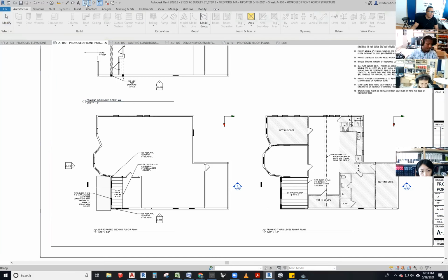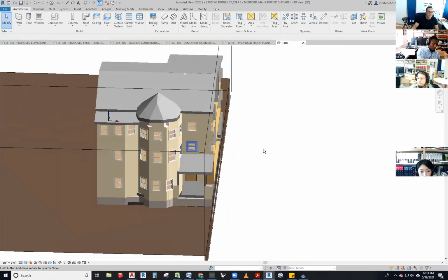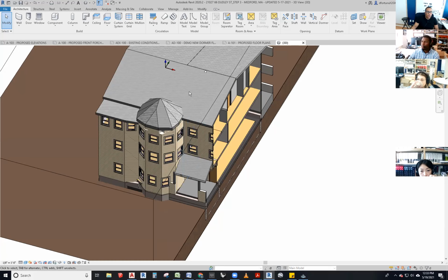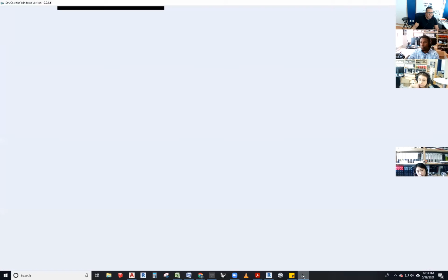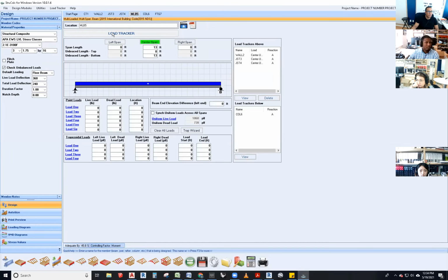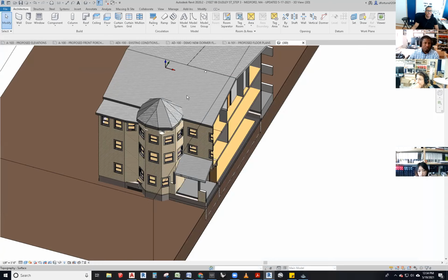Now you would say, well, we never told the beam how big this wall was going to be. Well, the wall is as big as the beam. We told the beam how big the beam was going to need to be. The beam knows how much of all of this, because the beam all the way back asked for the span of the beam, the multi-loaded beam. So it's supporting 13 feet of wall and 13 feet of roof with collar tie.